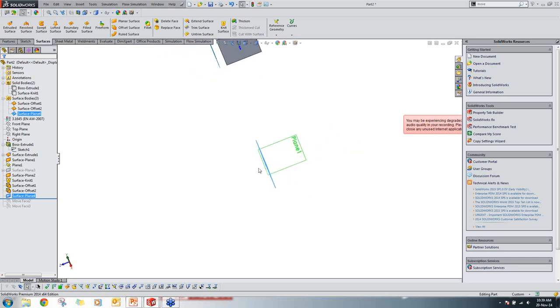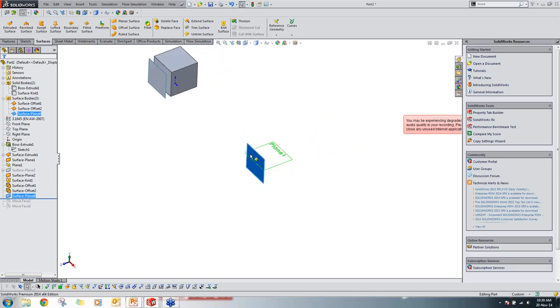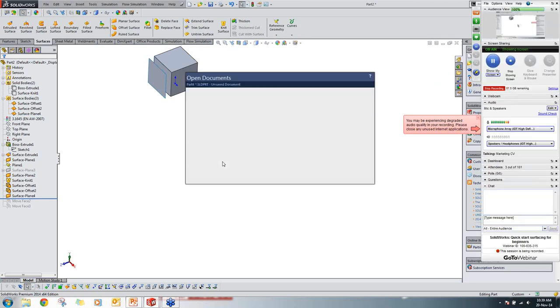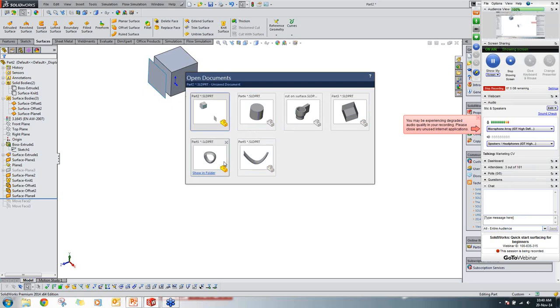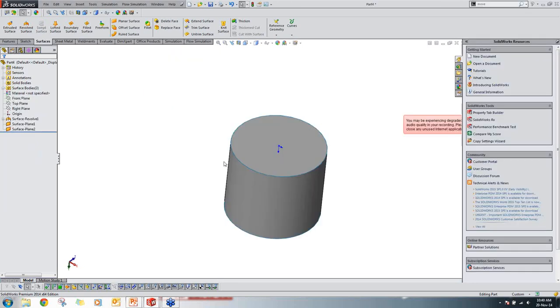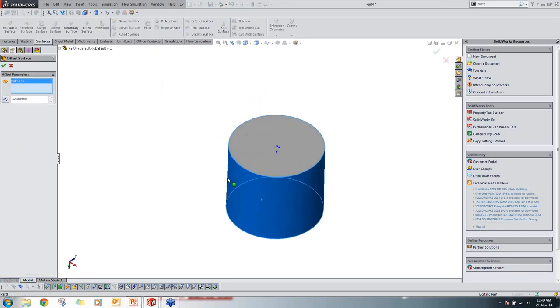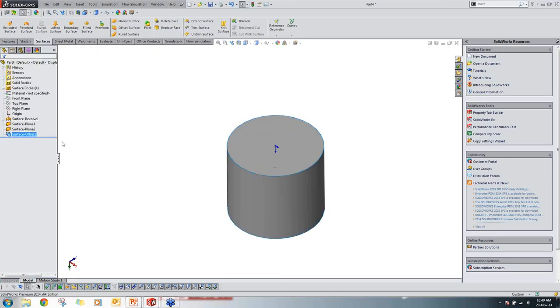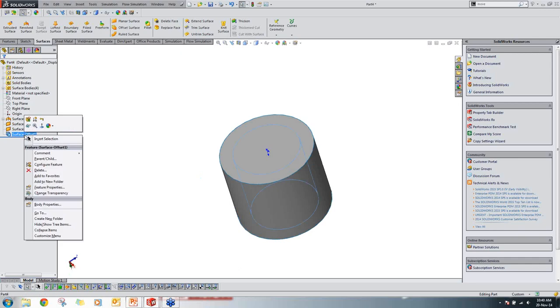Okay, so a surface body is created by using a solid body. So this is like a planar space, correct? So let us see a curved, circular surface like a cylinder. Same thing. We can offset the surface 10 mm. It's offset inwards.